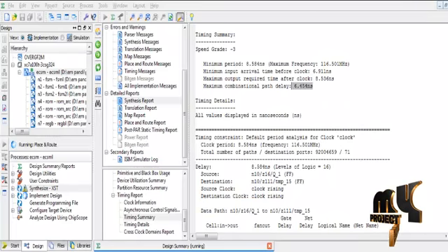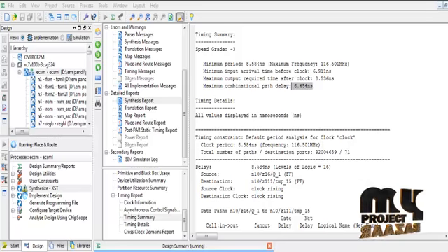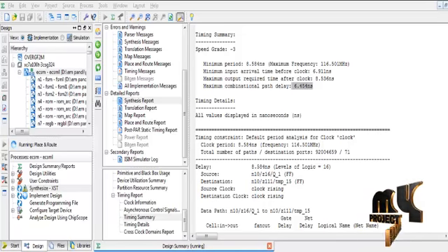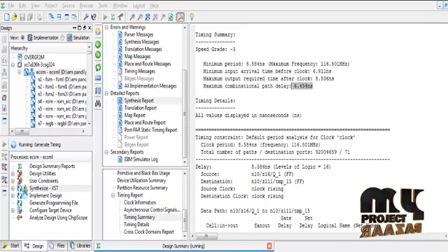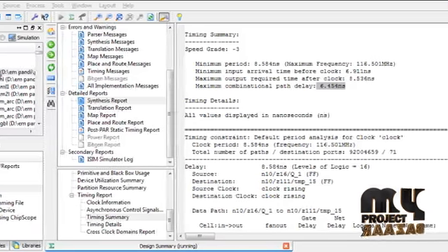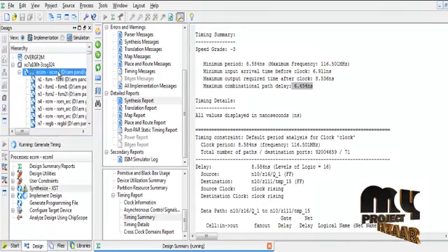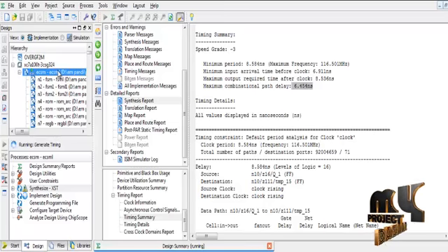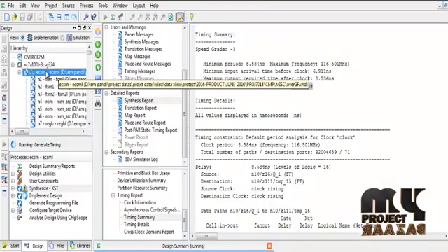Next we see the running process of our product. Our product is done in Xilinx 14.2 version. First open the Xilinx software, then the window opens, create a new project file and give the project file name. In our product, the file name is ECSM, that means elliptic curve scalar multiplication.